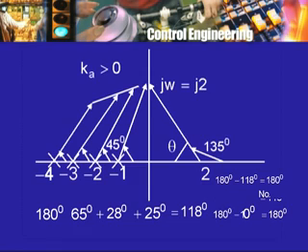And of course we had found that out earlier by using the real axis rule. Why? Because if you consider this segment of the real axis, then for any point on this segment, the number of poles and zeros to the right is odd, in fact only 1, and therefore that point is on the root locus. So we have found out one intersection with the j omega axis, but there may be more.